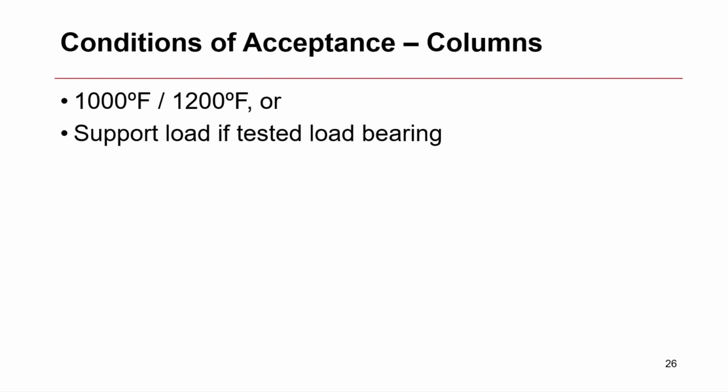So one might ask, well, is testing a non-load-bearing assembly representative of an actual column in the field? Well, the reality of it is yes, it is. And the reason I say that is, there are furnaces both in Asia and in Europe that can test load-bearing columns. And the correlating fire tests that have been done between the temperature-based criteria and the load